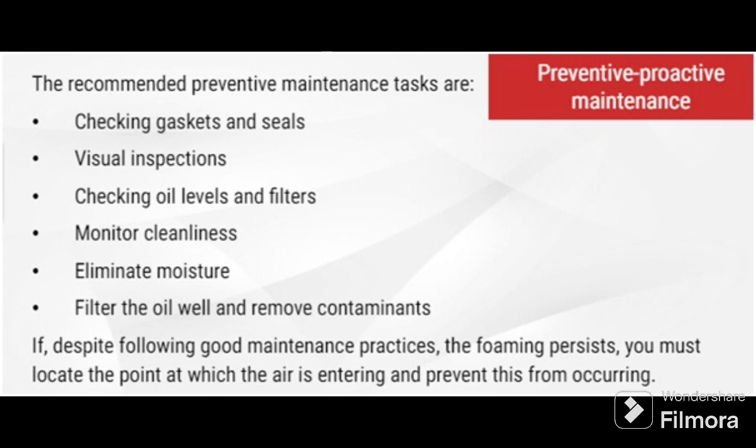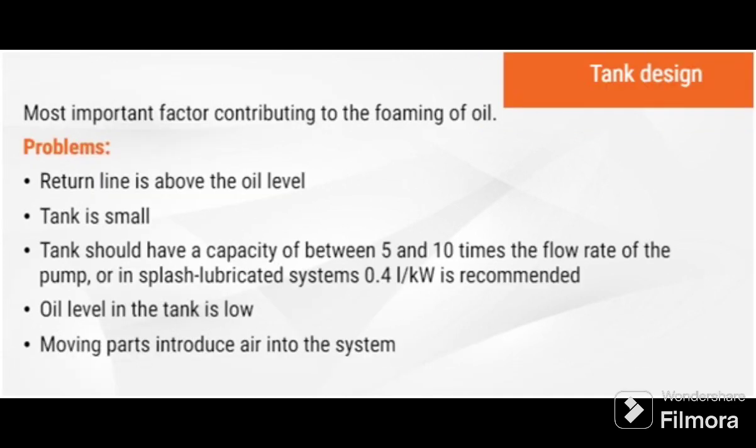In addition, it is advisable to monitor cleanliness, eliminate moisture, filter the oil well, and remove contaminants. If despite following good maintenance practices the foam persists, you must locate the point at which the air is entering and prevent this from occurring. Tank design is usually the most important factor contributing to the foaming of oil.